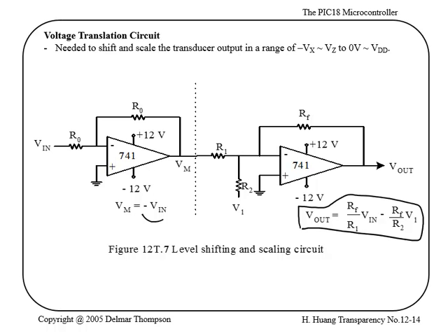Now you can use this to do a shifting of the level. So if you want to map, let's say, a 100 millivolt to 400 millivolt signal to your 3.3 volts and 0 volt, then you can use this circuit, plug in the values so that you can do this and get rid of the offset.